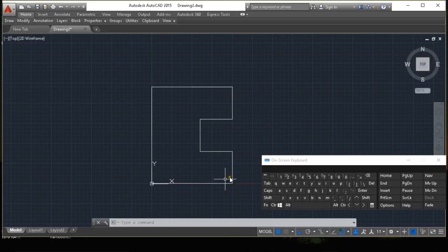In order to create a 3D diagram, you have to follow the extrude command. To use extrude, you have to use region first, and only after that extrude. Otherwise it will collapse when creating the 3D diagram. Now the region command asks in the dialog box to select objects.